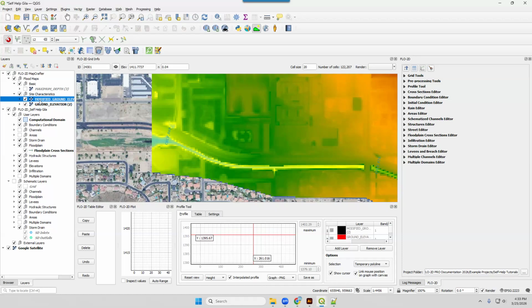And along outflow boundaries, if the node at the boundary looks upstream and sees that its upstream neighbor has a lower elevation, it will reset to 0.1 feet lower than the lowest elevation of its upstream neighbors. So that way you get the boundary condition, you get that normal depth flow. You can't have normal depth flow if your grid element is looking upstream and seeing a lower elevation. It can't be calculated. Okay, what's next?